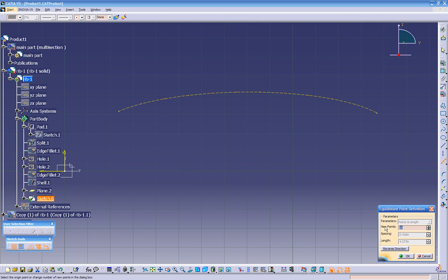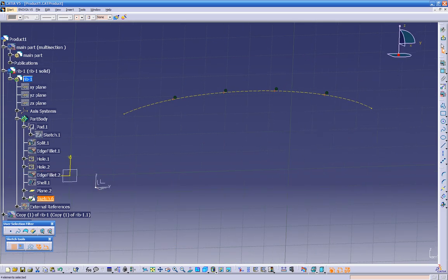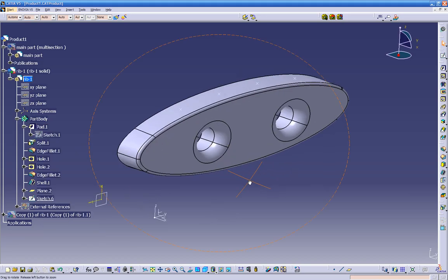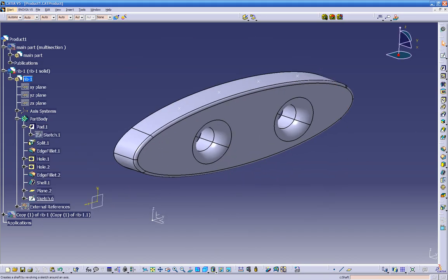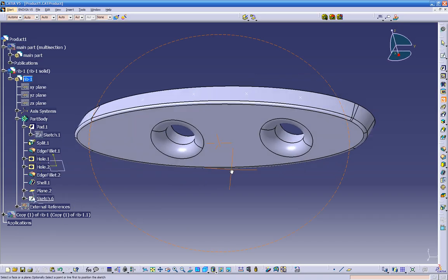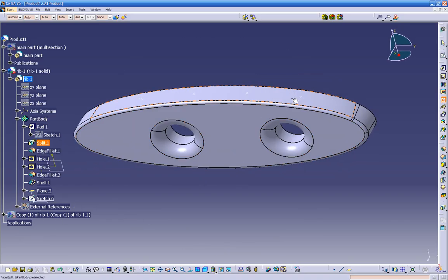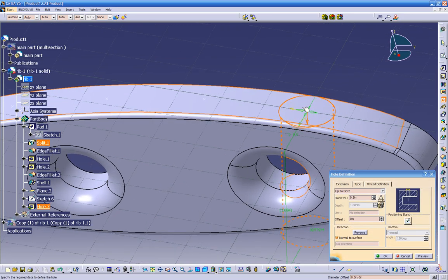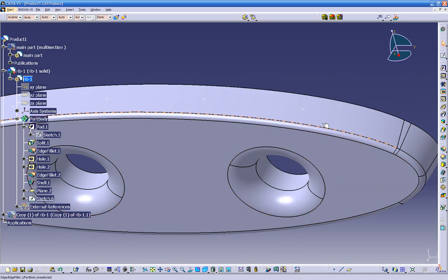And let's go 4, click OK, and we have to make sure we turn this option on. We get out of the sketch. There's our points. Let's bring the part back on, and let's create a hole perpendicular to the surface. So I have to make sure, let's cancel this, that I selected my point.